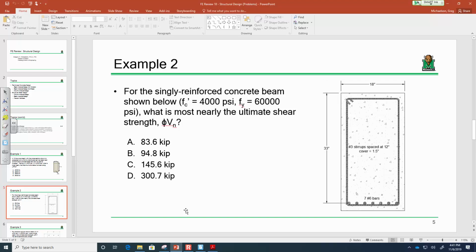Because the way that shear design worked in class, you could always, first off, does anybody remember what the shear capacity is a function of? It's a function of the VC and the VS, right? And so VC is the shear capacity provided by the concrete. We would always have loads on the structure, and what we would find is that VC wasn't enough.